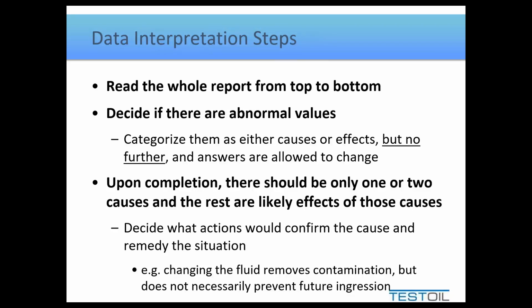Now, the little tidbit I put here at the bottom is I'll assure you that recommending an oil change is seldom the correct answer. It's a very common answer, I'll admit, but a lot of people who do this are not doing it correctly. Right? Suggesting that changing the oil fixes the problem does one thing really well. It makes the next report look good. But you didn't fix anything. You just erased the evidence that said something bad was happening. So the problem will likely return, depending on what it is. But more times than not, changing the oil doesn't actually fix the true issue.